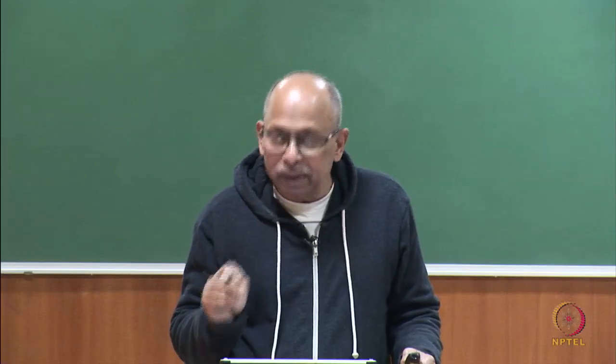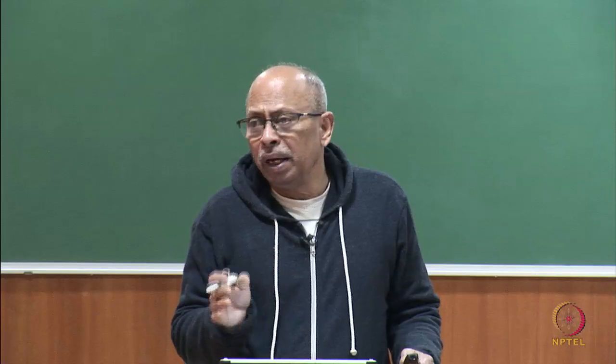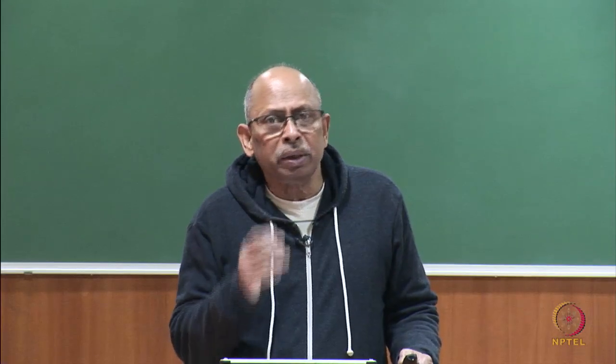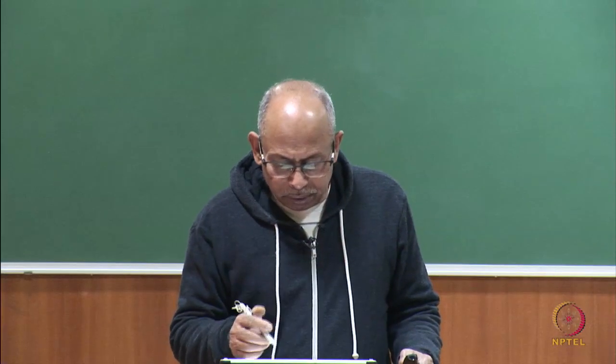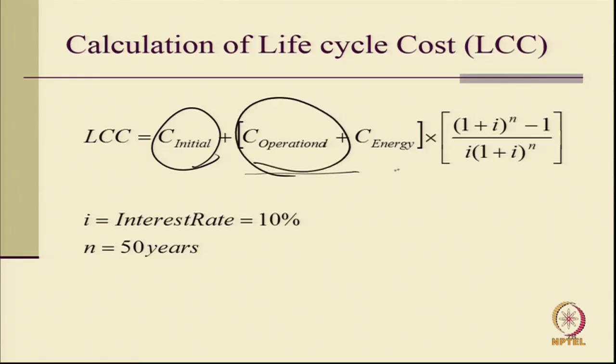And if you are using financial evaluation, then you can calculate the energy load and the cost of the energy. The operational cost that we talked about in the beginning is the operational energy. So, economically, you can look at the initial cost of the envelope, the operational cost and the energy cost, and then put the present worth with some interest rate.